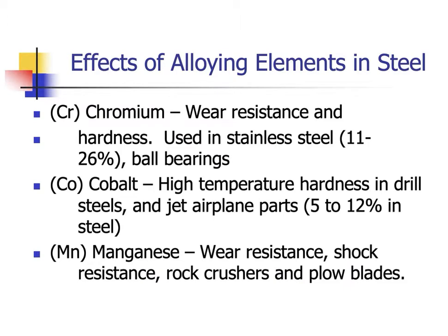It's actually probably made out of Corten steel, which means that it rusts. But once it gets an initial oxidized layer of rust on there, it doesn't rust anymore because that particular oxide of iron is impervious to more oxygen getting at it. So it's kind of funny that the reason why something is corrosion resistant is that it's not corrosion resistant. Okay, so cobalt.